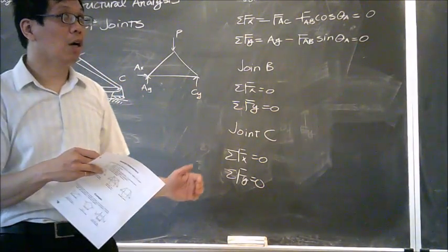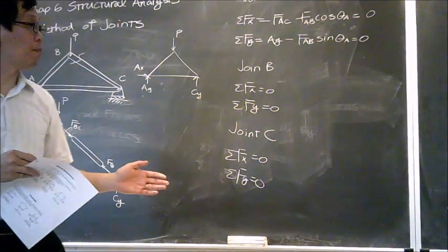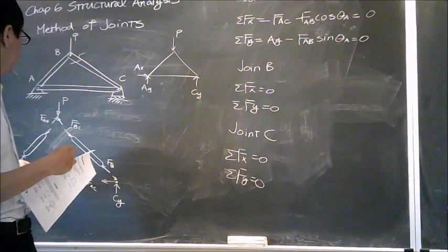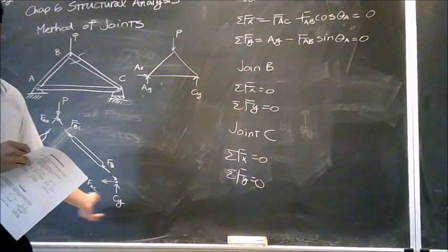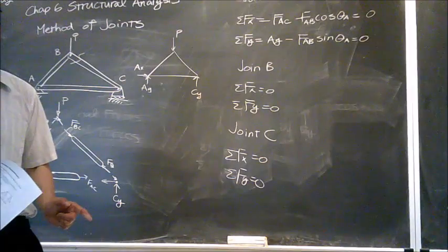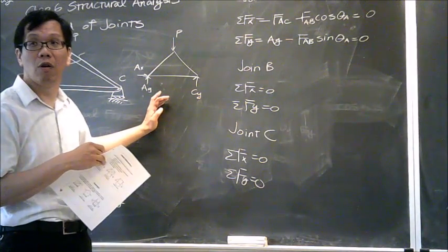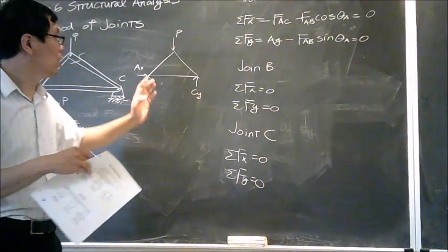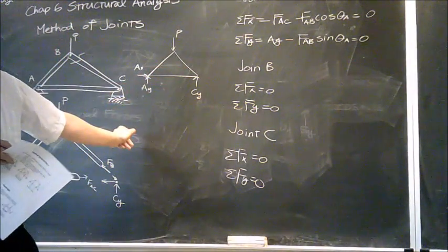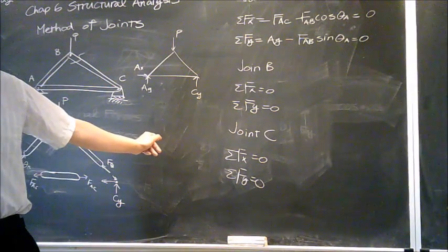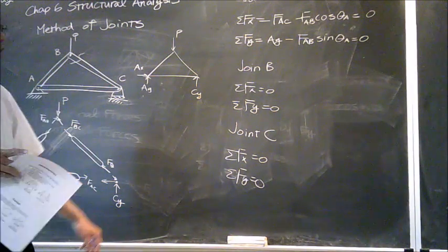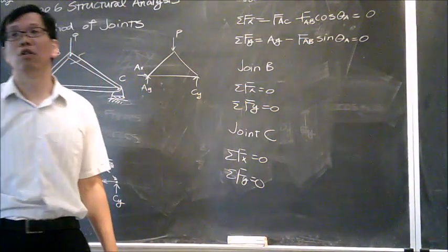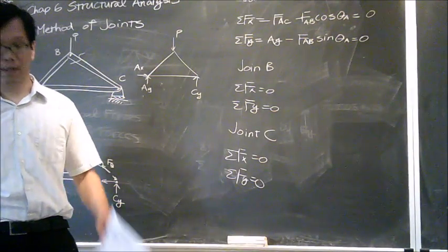Okay, so calculation-wise, it should not be that complex because you only have two equations, and chances are you're going to have at most 3 unknowns involved in this kind of equation. But keep in mind, you will need to treat the system as a whole when you approach this kind of problem and find all the external forces before you break it into individual members. That's the most important thing for this kind of problem. And once that's done, you just do that for two equations.